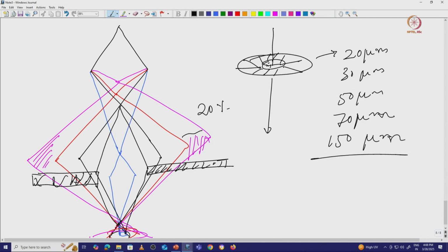So now you can see that I am using a very strong spot size or magnetic field, meaning that the spot size is 8, where the crossover point will go up. When the electron beam spreads like that, I will use a smaller aperture size and try to block the beam. Here we are blocking almost 50% of the electron beam.